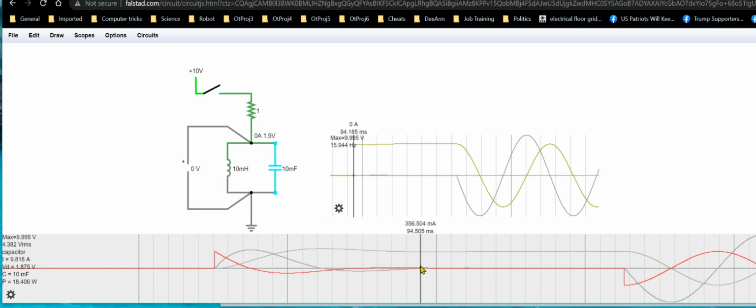By the time we get about here, the capacitor has basically dumped almost all of its charge, and the inductor is starting to discharge down to this, roughly 10 amp level, which is what you would expect given the fact you get a 10 volt with 1 ohm resistor in series with it. Well, that's going to produce a current of 10 amps.